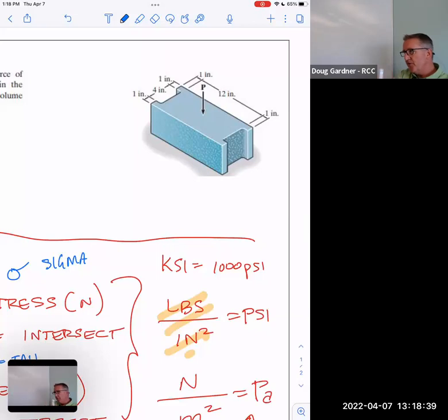So what I have to do is put a bunch of rebar in it both directions. Rebar, have you seen rebar? It's like 1/2 inch in diameter stuff, and I'll make a grid out of it going this way and a grid out of it going that way. And that way, when you do put a post in the middle, it will make it all act as one and sink uniformly into the ground.